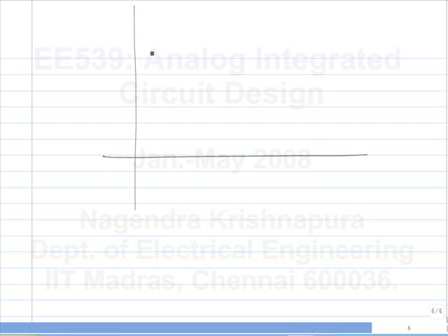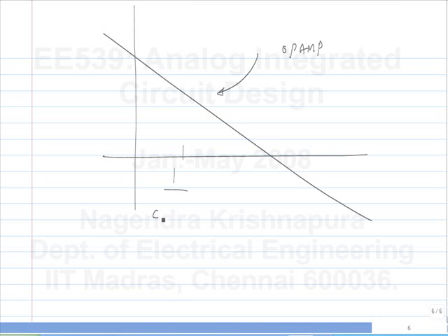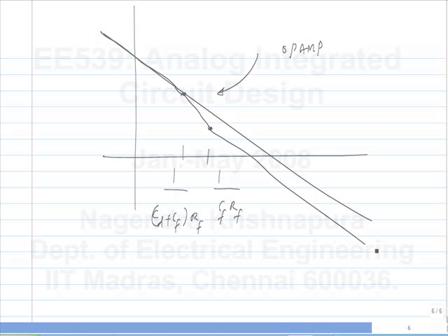So this is the op amp response, and the pole is at a lower frequency than the 0. Okay. So you will get something like this, and between these two you get a higher rate of roll off, and then it comes back to this. And we discussed earlier that if the slope is 20 dB per decade, when it crosses 0 dB, it is a stable system. Okay. So this is what you want to do.